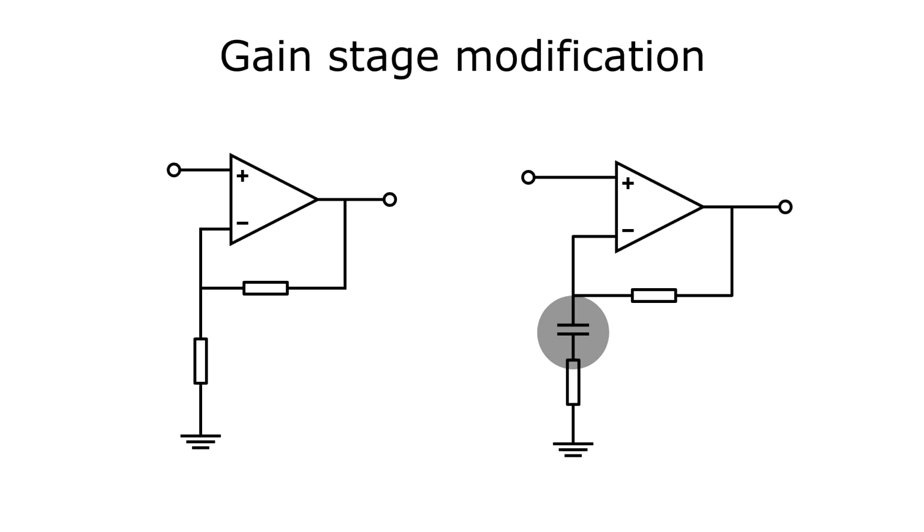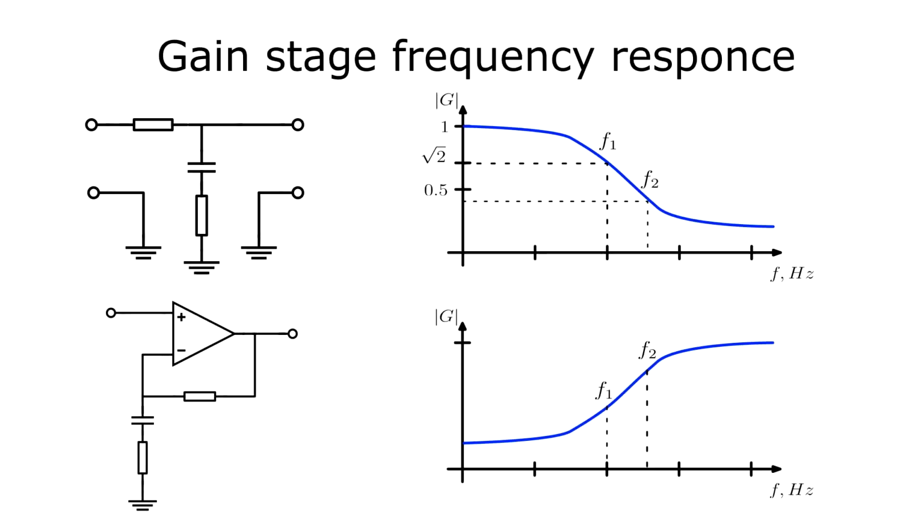Let's return to our gain stage. To reduce low-frequency saturation, we can use a shelf filter instead of a voltage divider in the feedback loop. However, it's important to determine the type of the filter. It's worth noting that the frequency response of the filter is different from that of an amplifier. To understand the relationship between them, we can plot the frequency response of the amplifier based on the shelf filter